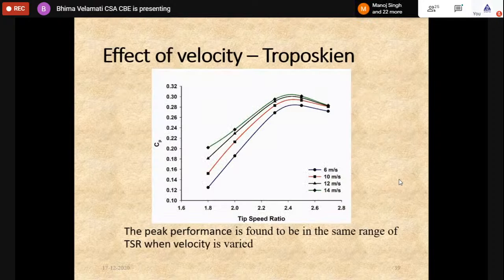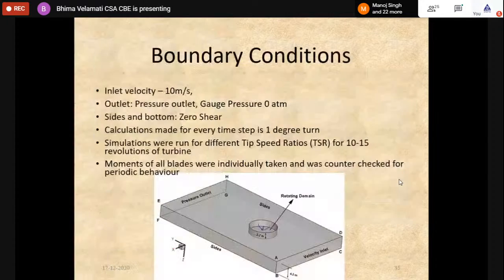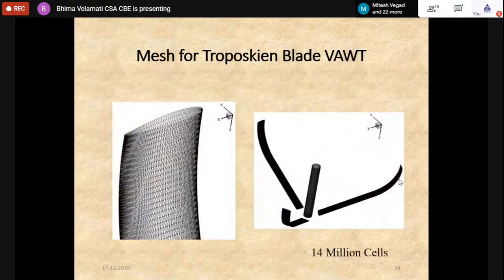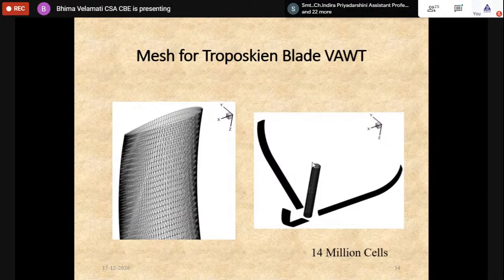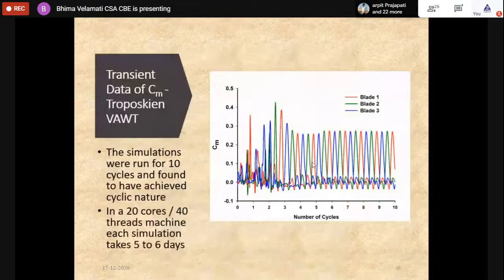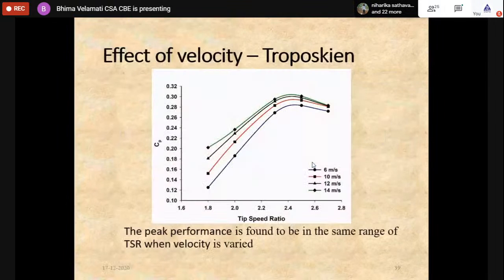Whereas with the proposed skew blade, you will have that problem. Okay, I will show you the proposed skew blade again. See, here the radius is changing. The radius of the blade is changing with respect to height, the z direction. That means omega r is changing. So you expect that each section of the aerofoil is encountering a different velocity, or different Reynolds number. So we were interested to see what would happen if the wind velocity is changing.